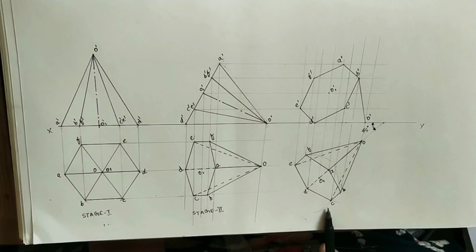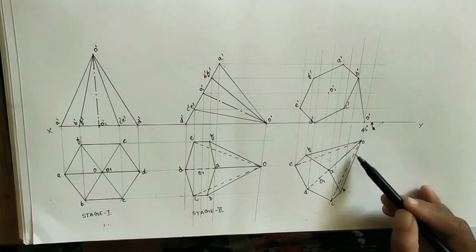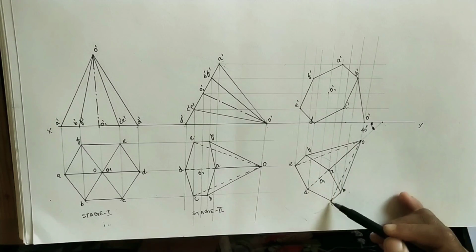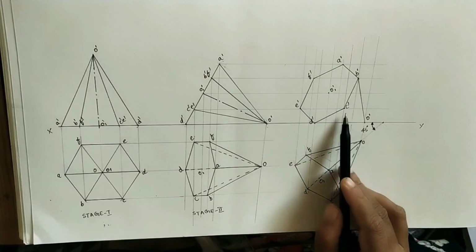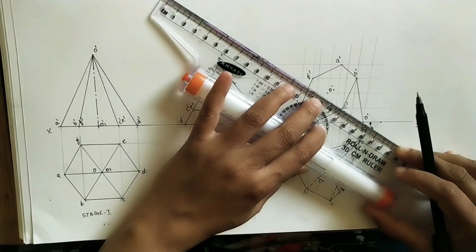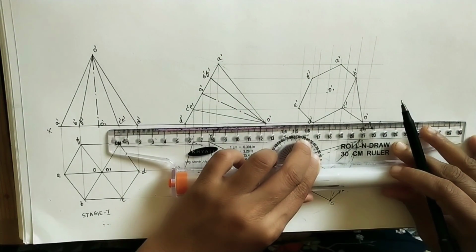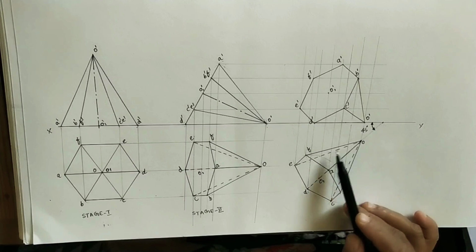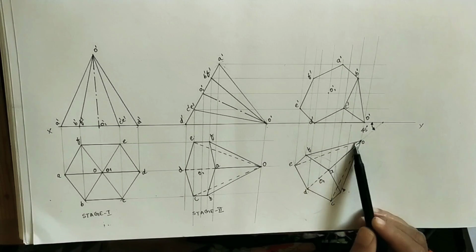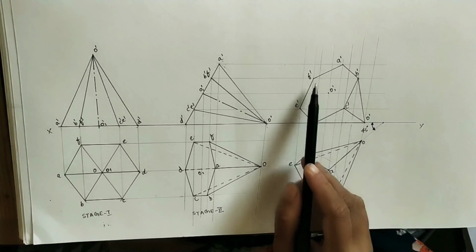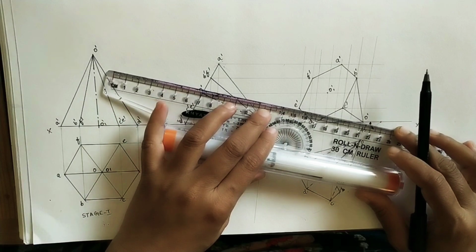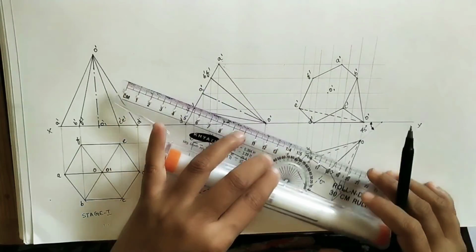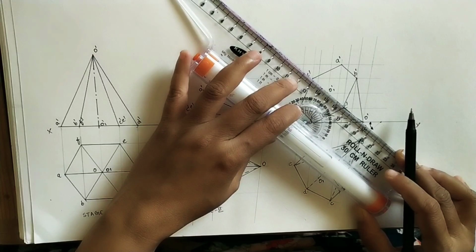So if you see from this side, we can see OB edge we did just now. We can see this edge also. From this direction we can see this edge also. So from C to D, these C and D slant edges we can see from this direction. So from C and D, do the continuous lines to the apex. And after that, from this direction, we can't see these edges which are passing through E and F. We can't see these slant edges. So from E and F, join the apex with dotted line. Those are the invisible slant edges. And then from F and apex also, dotted line.